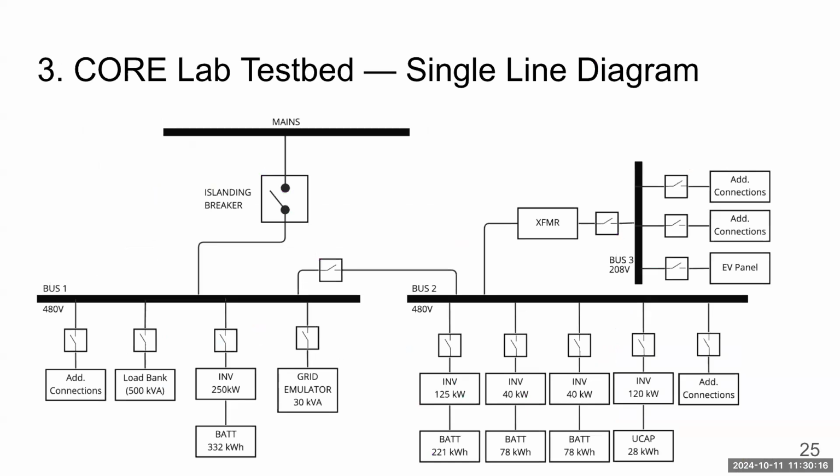Yeah. So the lab was also designed to be flexible like that, and the way we do that is what we call an emulator. An emulator is basically a combination of an inverter and a battery, and you can emulate any signal through this, because the battery can do anything that any other device on the grid can do. It can discharge, charge, real power, reactive power, fast or slow, so you can use that tandem of devices to do anything that you want to test.